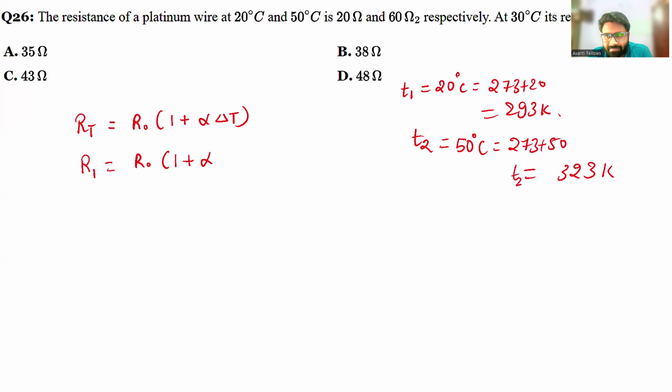Now, the value that we are measuring here is from the base value. So for resistance at 50 degrees Celsius or at 60 degrees Celsius, what will you do? Alpha into delta T, take the reference temperature as 0. Now, if I apply R naught into 1 plus alpha, alpha will not change.